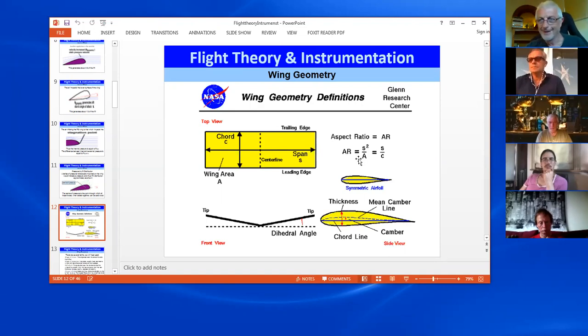You all fly wings. You're a paraglider pilot, so I'm guessing most of you probably know what the aspect ratio of your wing is. If you're on an A wing, it's probably 5.1 or something. B wings go probably from about 5, depending if it's a low B to a high B, anywhere from 5.4 up to maybe 5.8, maybe 6. C wings, you're generally going from about 6 through to 6.5, and then you'll get into D wings, which will be in like 7 aspect ratios, probably more like 7 to 8.